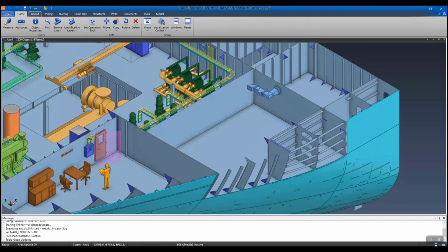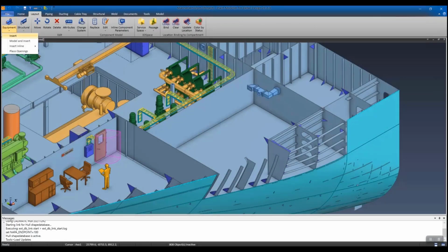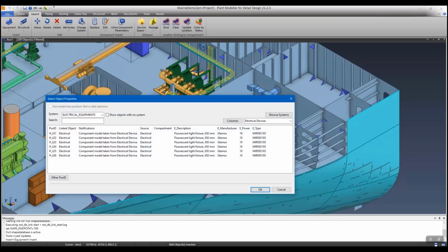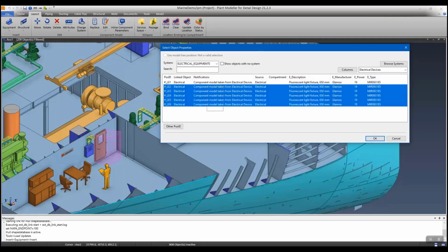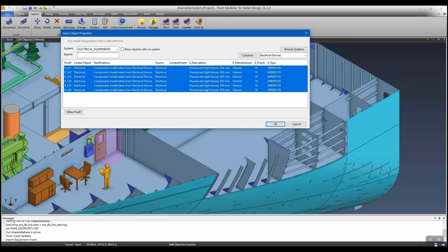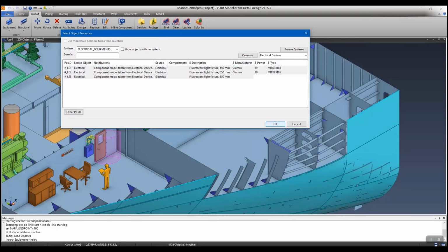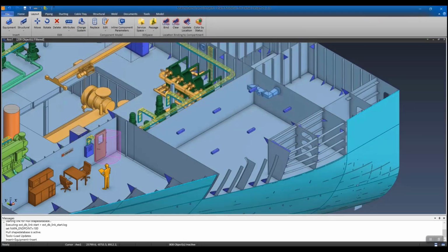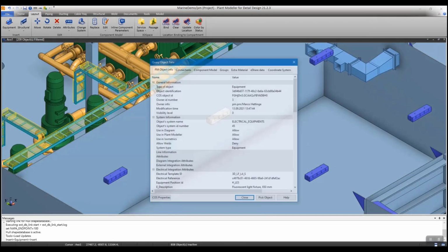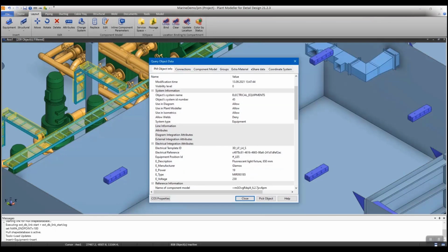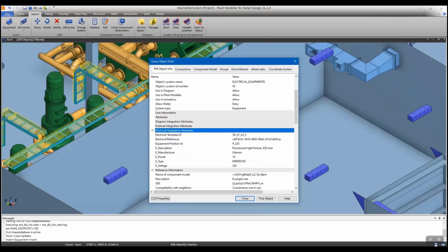After those are selected, these are available in 3D modeler. We can place the equipment one by one, or then when all are selected, we can also use multi-insert to insert the 3D models of the luminaires. We can see that the same metadata, same tag, same manufacturer information is now available also in 3D modeler.